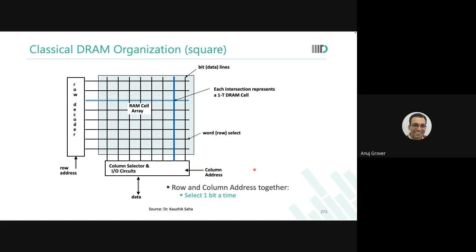See, with SRAMs we talked about this concept of mux early on. When we started with SRAMs, we said we need a mux. Why do we need a mux? Because we want to play with the aspect ratio of the memory. We want to have more rows, more columns, fewer columns, depending on my performance requirements, depending on the floor plan of my chip, so many things. I said I want to play with that. In DRAMs, you can't do that. DRAM arrays are always square.